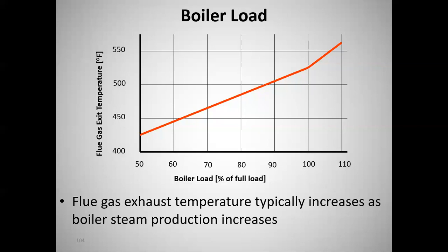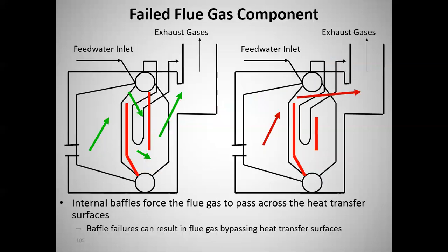So if you're going to compare stack temperatures, to have a fair direct comparison, I need to have the same boiler load, the same inlet air temperature, and of course, assuming that the steam temperature is the same in order to properly compare. Because sometimes you want to say, well, that stack temperature seems like it's creeping up. Maybe we need to open this thing and clean it. Oh, that's right. I need to show you guys the borescope video. I did find it. We'll do that here in just a second once we get finished with stack temperature.